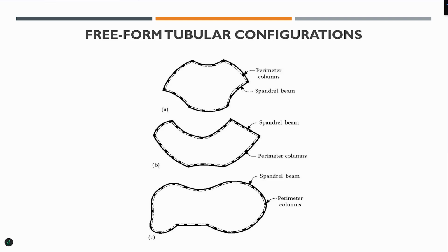But the problem was stress concentration. Whenever you have irregular stuff, the first thing is stress concentration. So the stresses in the columns were not uniform anymore. They had a lot of discontinuities and stress concentration. But luckily, by that time, we have computers. So now we can do the analysis. We can determine those things. So it starts to work fine.